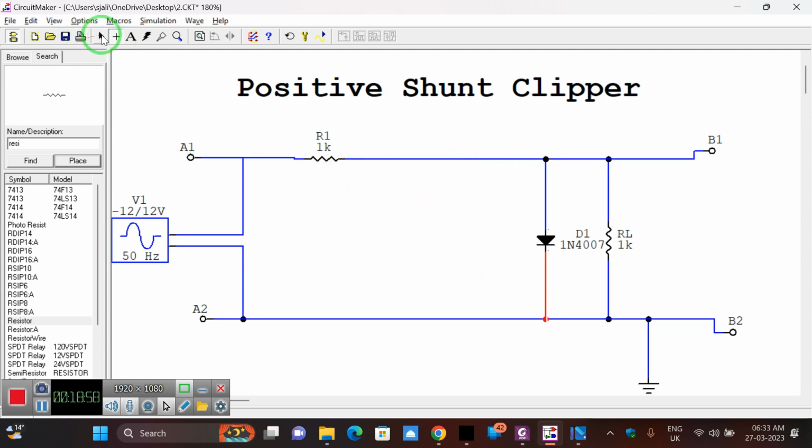Here then you use the arrow tool. So all the dots are here, means these are connected. Only here this is not connected. Now you can move this wire like this, then it is connected. Now you can save this one and you can run. And before that I will keep the probe here, 1 and 2. So okay, arrow tool.